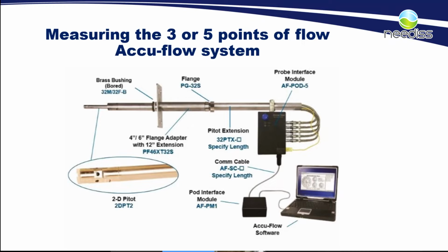Depending on the accuracy that you need and what's determined by local regulations, these particular systems could save hours and hours of sampling time, doing 4 pitots at the same time rather than doing 1 and traversing all the way around the stack.